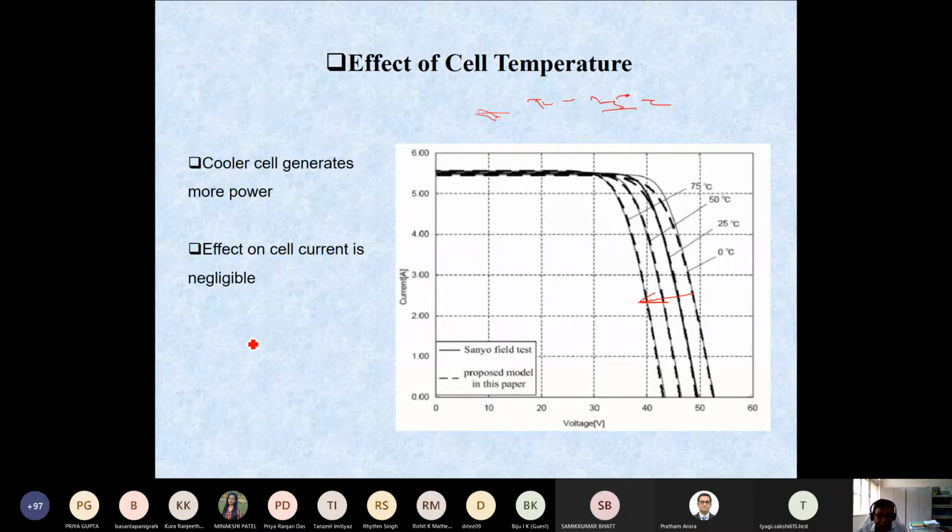So you can find the voltage as the initial or rated voltage minus that factor, dV, multiplied by the temperature rise, that means the cell temperature minus 25 degrees. This is given in millivolt or volt per degree centigrade. So any increment in the temperature is multiplied by this factor and the voltage is reduced accordingly. That is the factor we have to consider.